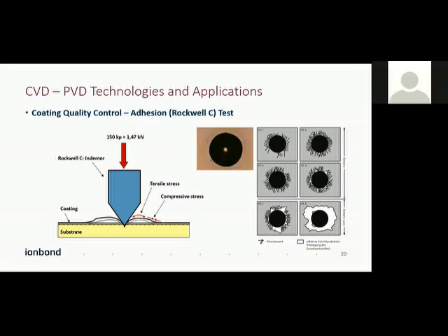So in hot forgings, are PVD coatings used for press forging dies or for extrusion punch tools only? These PVD coatings can regularly be used in hot forging. Right now, the big hot forgers in India, like Bharat Forge or MM Forge and those, we regularly do these PVD coatings for them. So PVD coatings are very well possible on forging dies, and they give a good advantage with respect to increased productivity.